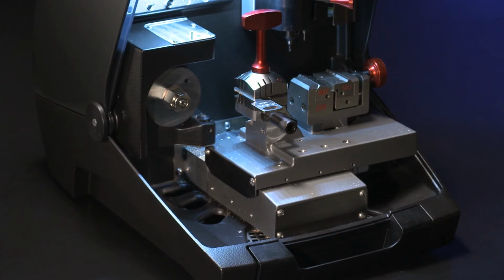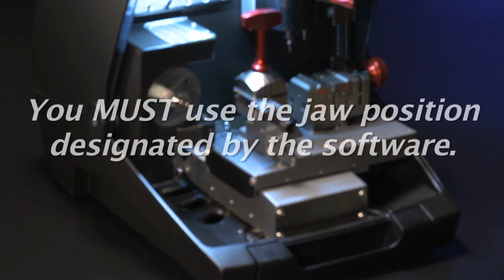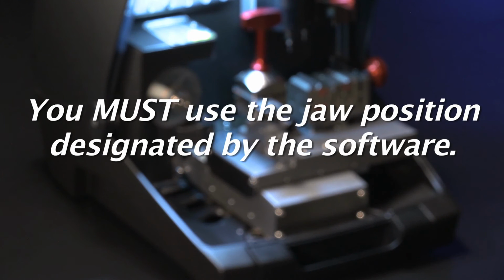Tip: Futura Pro's database will indicate clamp side A on most two-sided automotive keys. When you are decoding a key, you must use the jaw position designated by the software. As mentioned earlier, when manually entering the cuts or cutting by code, the user can decide which side is most suitable as long as the Use Any Clamp feature is enabled in the software.